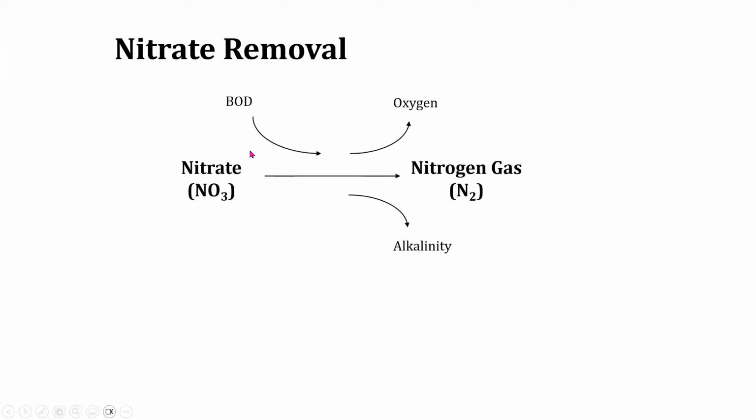Then the nitrates that get produced in that aeration mode during nitrification, so you're denitrifying, converts to nitrogen gas. Nitrogen gas bubbles out of the wastewater, goes to the atmosphere. The atmosphere is 3/4 nitrogen, not polluting, it's going home. Requires BOD. Often BOD is a limiting ability to drive nitrate removal.